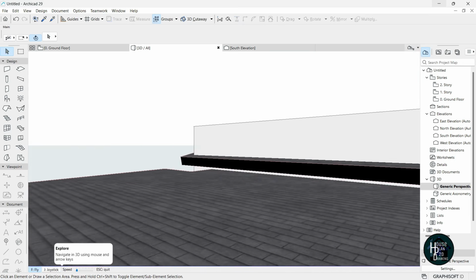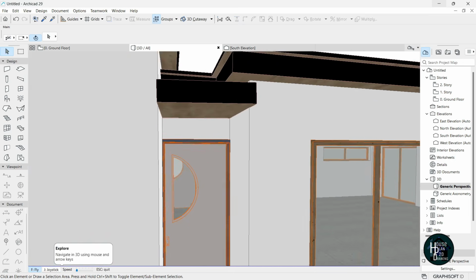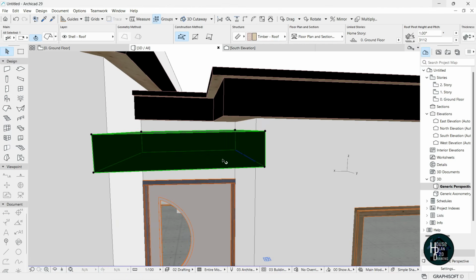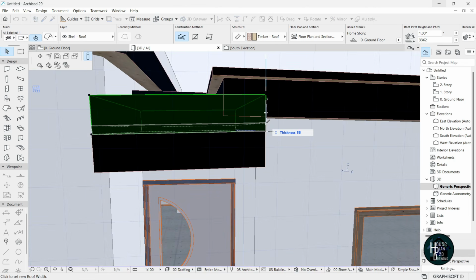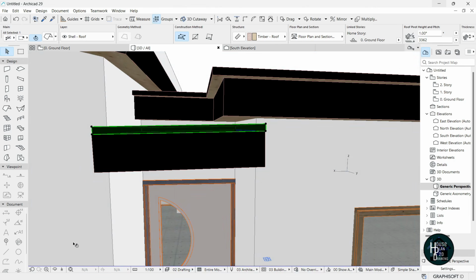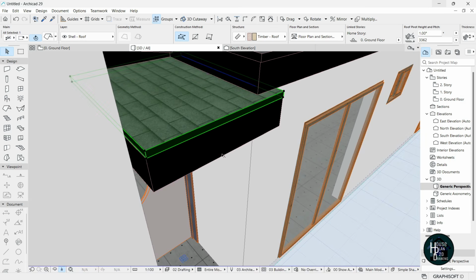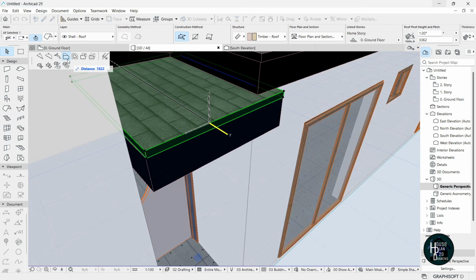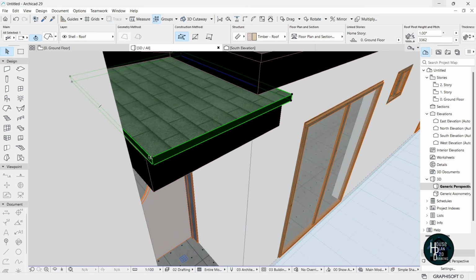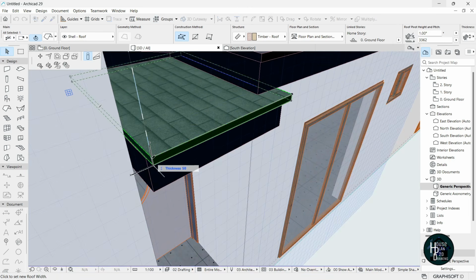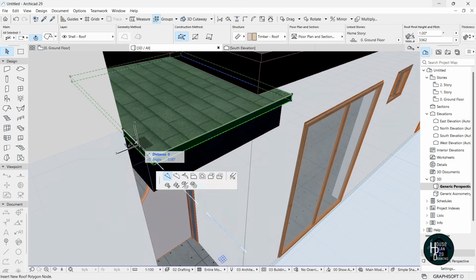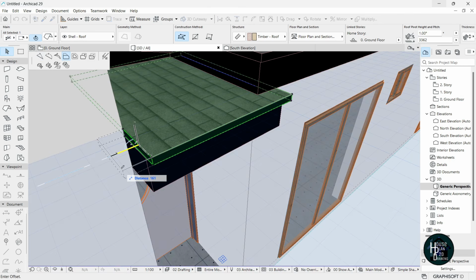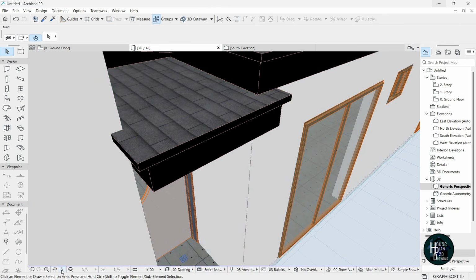now for this other side here, we're also going to be doing the same thing. Click this, press Ctrl Shift D, and let's make a duplicate of this, and then we're going to be reducing this by 50, and then we're going to be offsetting by 80. Okay, click on the offset and offset this one by 80. All right, you can also decide to click on the node here, or click on this edge here and then start a new node close to the wall here. Click this edge, select the offset edge and offset this edge by 80 also, so it has that design to it.